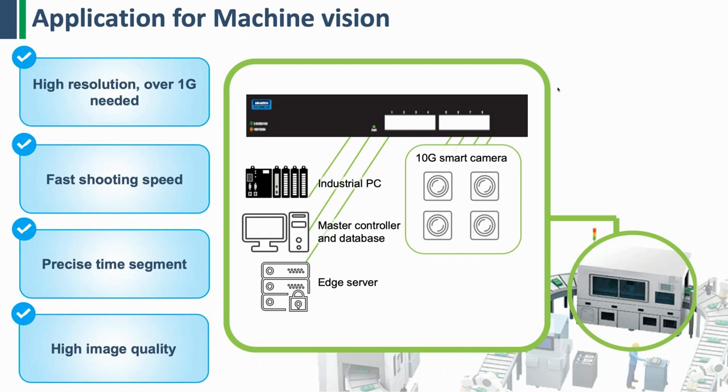Another challenge with machine vision is frame rate. A standard camera, say one installed in the street for number plate recognition or security, normally shoots anything between 16 and 24, maybe 30 frames per second. Quite often in machine vision we're using cameras with a much higher frame rate, sometimes 120 to 240 frames per second.